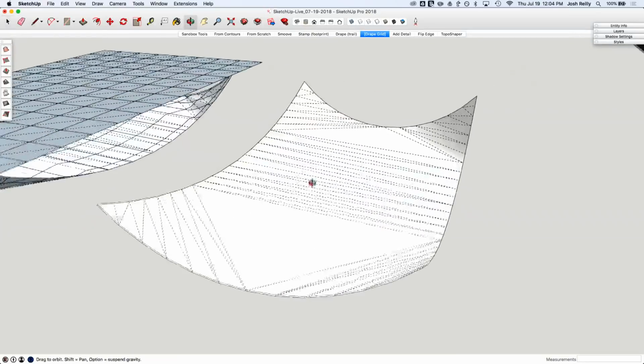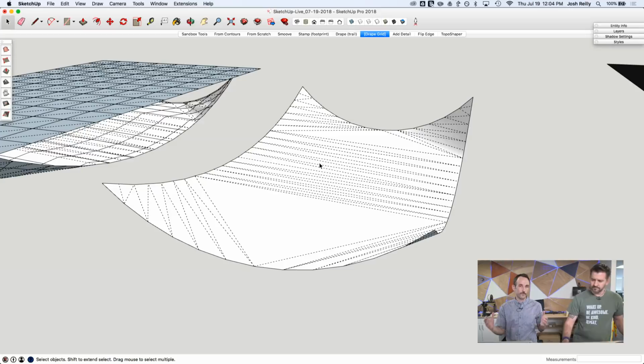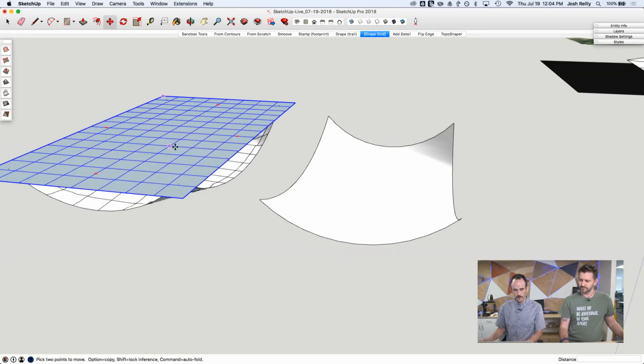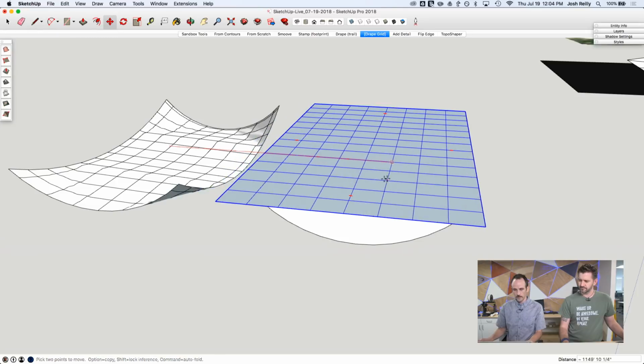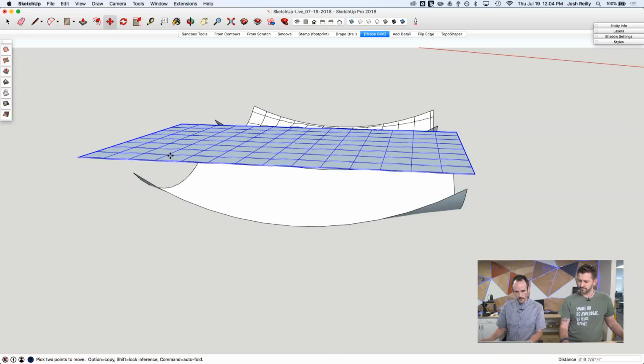And this may not be the most useful polygon breakdown of this complex edges. So if we had more of a grid, that'd be pretty useful. So kind of a sneaky use of this tool in SketchUp, the drape tool, is I can actually drape a grid down below. So let's move this grid over top of that more complex surface, make sure it's looking good. And I'll move it over this way a little bit.